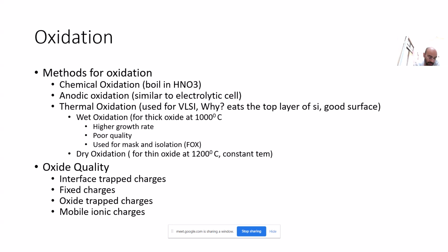But then the problem of using halogens is that if the concentration becomes too high, then pitting can take place. Okay, so that is pitting of the surface. Pinholes can be created in the oxide layer also, and small pits can also be created. So that is the disadvantage of this. You can use this, but the concentration should be in very small quantity.